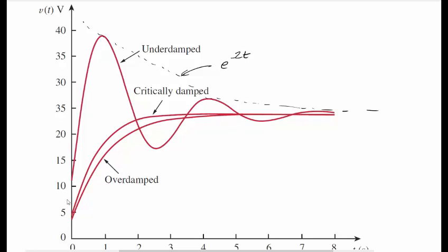Critically damped and overdamped never look significantly different, but they always had the same kind of shape. But we differentiate critically damped because the moment you get past critically damped and into the underdamped, the oscillatory behavior will begin, and there will be a slight overshoot and a slight oscillation, which the more underdamped it is, the bigger this oscillation will be.